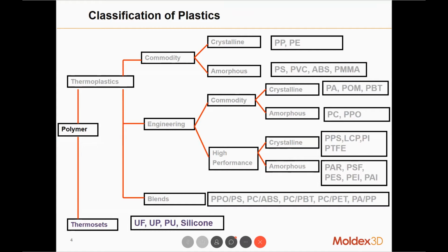So for thermoplastics, commonly we see PP, PC, PA, ABS, a lot of them, and some polymer blends. For example, PC and ABS. Sometimes we can see PC and ABS in our suitcase when we travel. Okay, and then we have another category, the thermoset, including polyurethane, PU, silicone, liquid silicone rubber, and just rubber, a lot of different epoxy, etc. So these are thermoset materials.